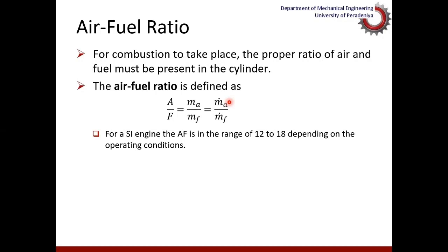Now, spark ignition engines, as I indicated earlier, we need to operate around the stoichiometric air-fuel ratio to get the best outcome. But in certain situations, we prefer to have rich mixtures, and in certain situations we prefer to have lean mixtures. As I mentioned in one of the previous lectures, at cold start, we prefer a rich mixture, in the sense of an air-fuel mixture with more fuel in it than the stoichiometric, so that we can initiate the combustion easily.